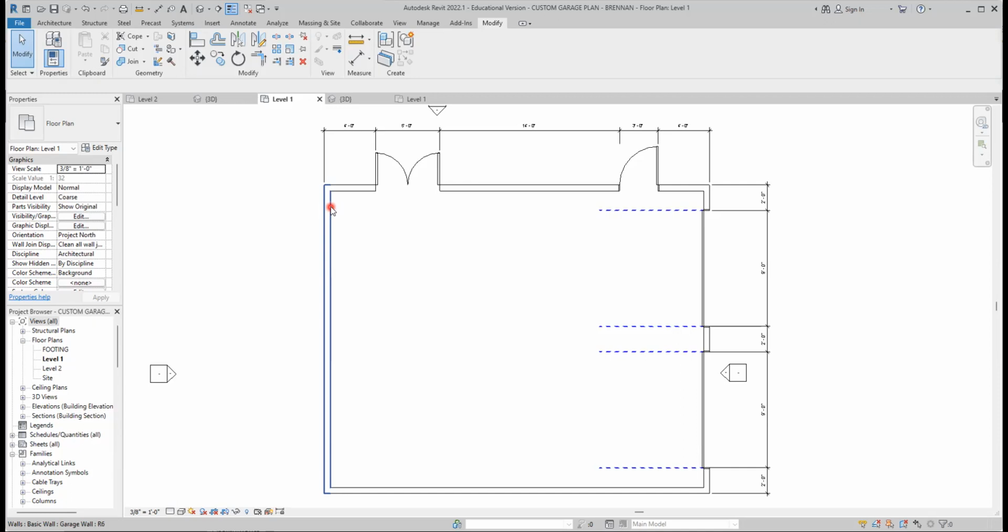Now what we just did there, that's the worst of it right there. And I am serious about this: when you're working with Revit, that little exercise that we just had, learning to zoom in really closely and dragging those witness lines into position, is a skill set that you will use if you're going to do Revit. As long as you're able to manipulate those temporary dimensions, you are able to do anything. That's why I put that in there. I deliberately made it kind of a pain in the butt. So anyway, now you got that. Now you understand how they all work together.